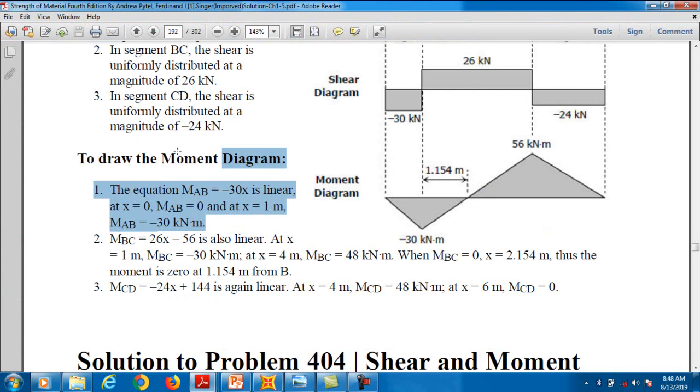So this is very important, because whenever we are doing our design, basically RCC design, reinforced concrete design of the beam, we need this point, because at this point of inflection we check the development length for the positive bars and for the negative bars. So for that purpose we need this distance sometimes. Okay, and for that purpose the importance of this point is very great.